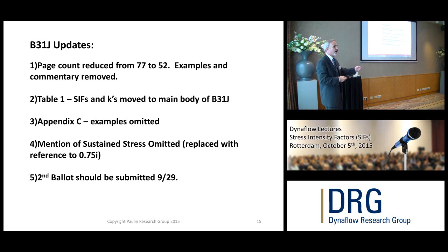So what's in there now is it says if you're doing a sustained stress analysis and you've got the term 0.75i in your equation, take 0.75i out and replace it with this. And we give you the new term for it. So you don't see SSI, but you see a replacement for 0.75i. So that's the sustained load guidance now. And everybody's happy with that, because all the code books can use it, and B31.3 can use it also. Because B31.3 says in lieu of I, use 0.75i, for a sustained load.